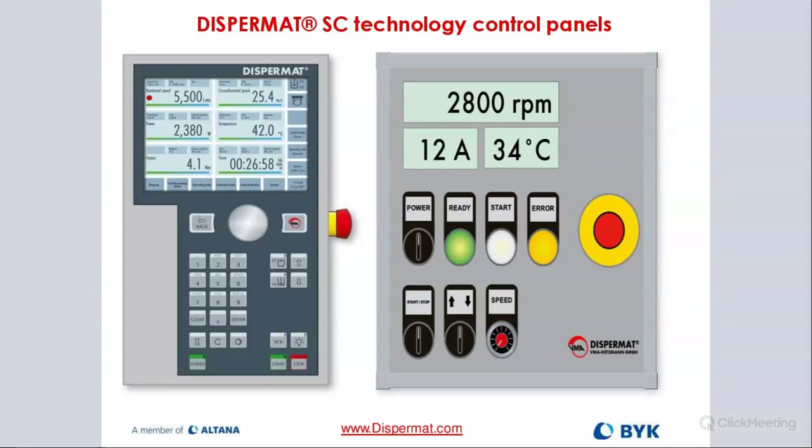So by having a torque value, I'm able to see that really clearly. We also, on the standard machines, express the torque value obviously in Newton meters, but it's a calculated value from the frequency inverter. We have a TMS sensor, which is basically a special sensor that's ordered separately that goes onto the shaft, and that actually measures, not calculates, the torque value directly on the shaft to a resolution of 0.1 Newton meters, which